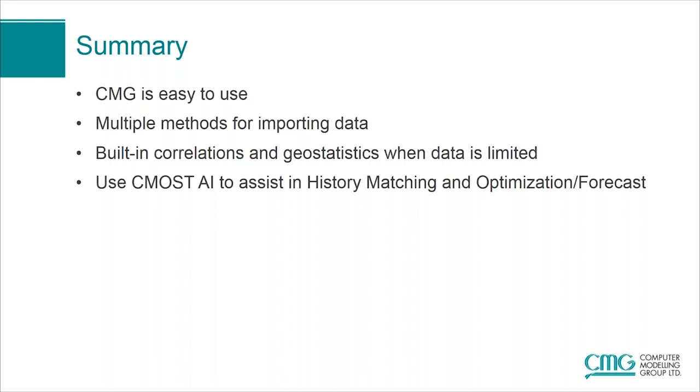The next question is, can the hydraulic fracture wizard be used to simulate a non-sealing fault? Is there another way to do this other than the dual permeability or porosity model? And I recognize the name, this one is a long-term user of CMG. So basically, there are several ways in which you can actually model a non-sealing fault. The traditional way is to define the fault and you can model the transmissibility.